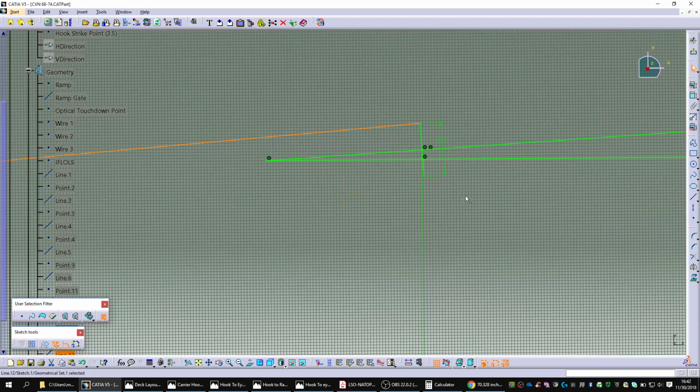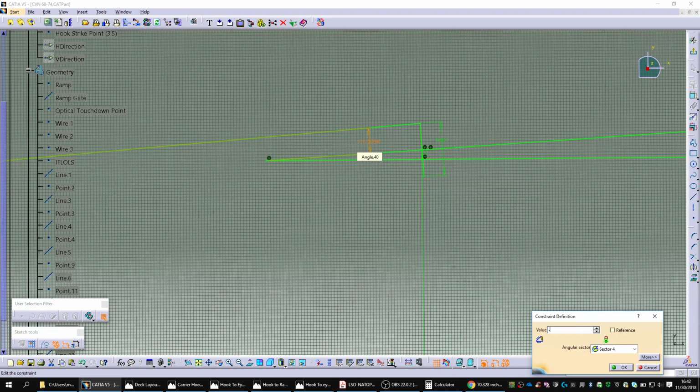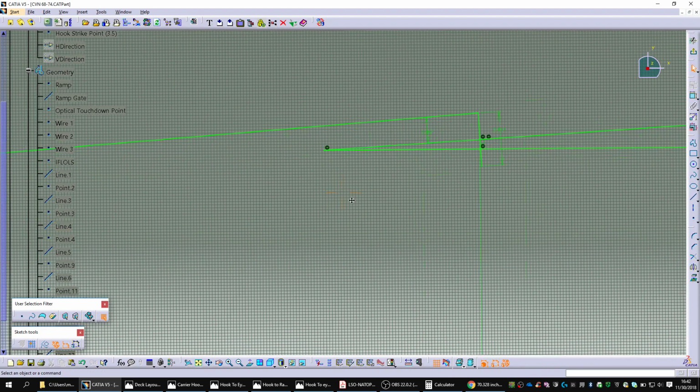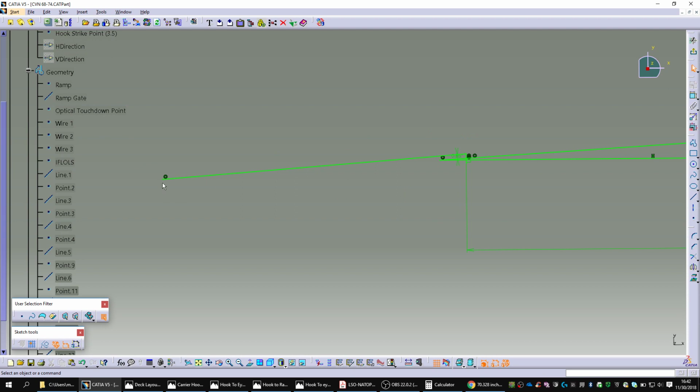And you know what? I'm going to constrain that angle, because that will fully constrain it. So I know that from top of this to bottom of this is 1.7, but half of that is 0.85. Hey, what do you know? That's fully constrained now. And so that, by definition, has to be the focal point. We'll confirm it on the bottom.